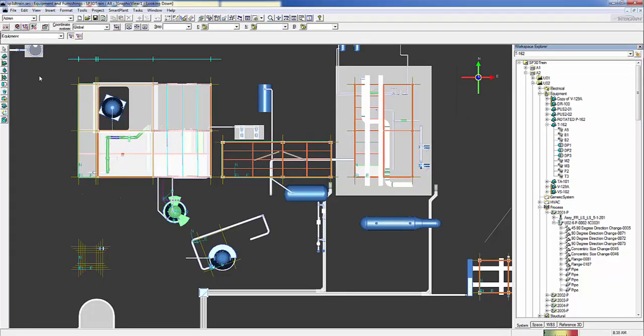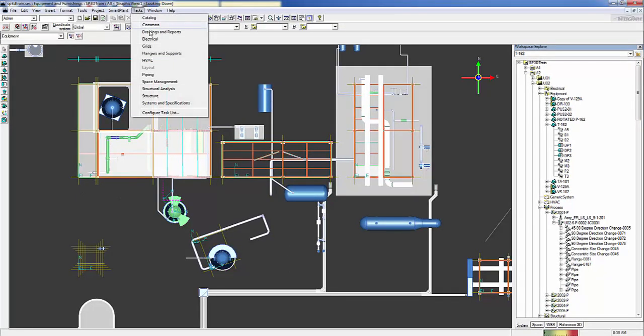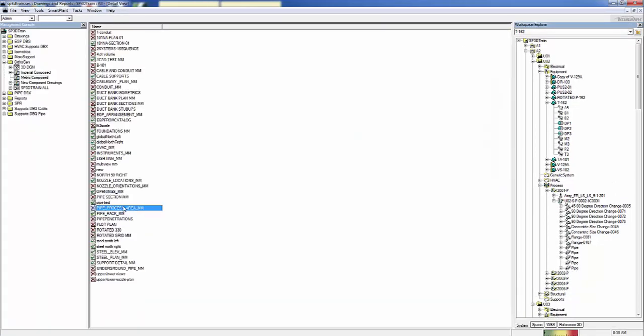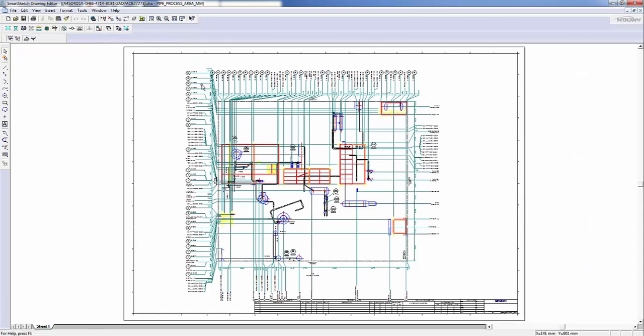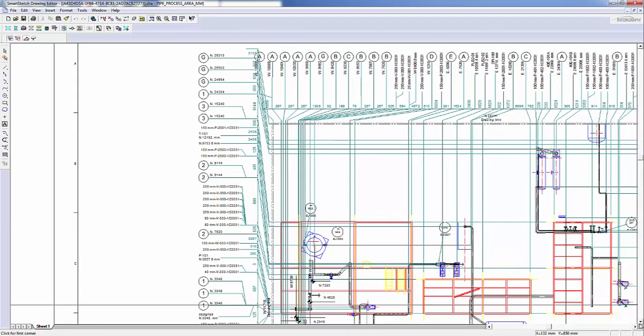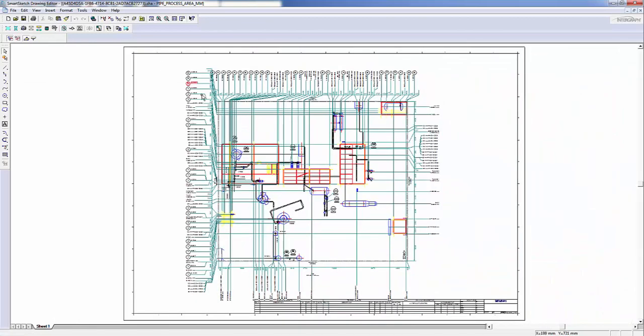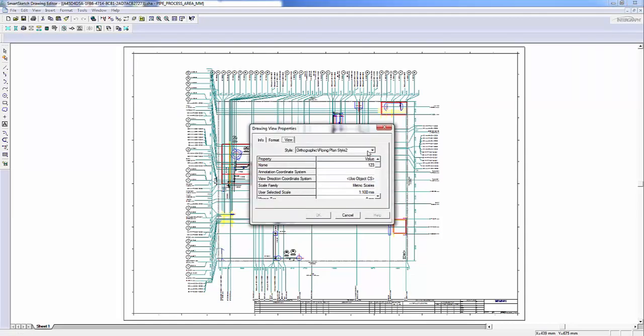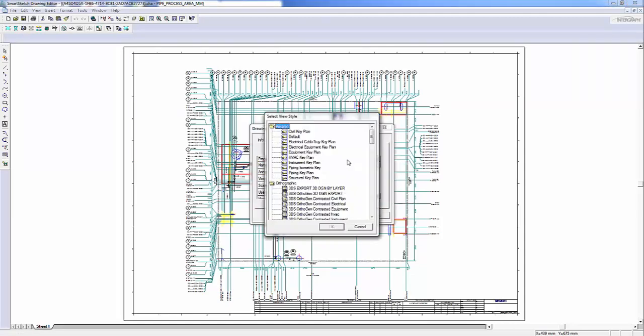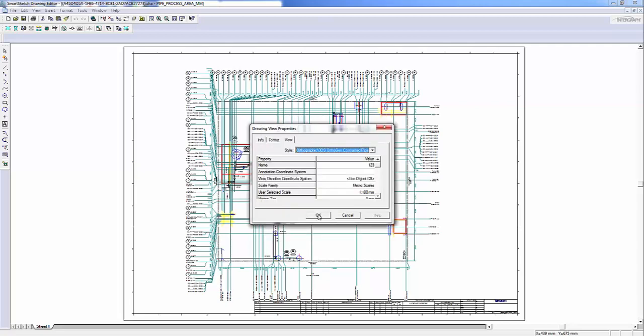Let's switch over to the drawing task and edit a drawing in S3D. This drawing was previously updated using a view style delivered with S3D. This style produces the edges graphic view and also adds the dimensions and annotation. Orthogen delivers simplified view styles that only produce the edges graphics. You can configure S3D to place things like title block data, view, and match line labels. Even flow arrows will be treated as edges graphics.